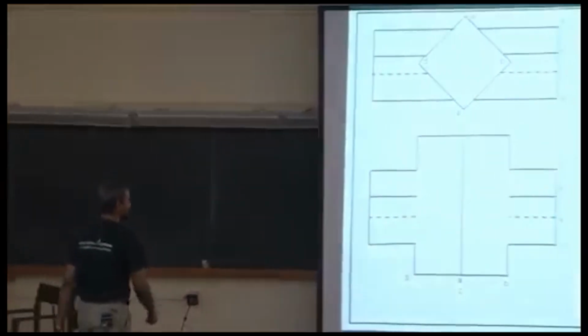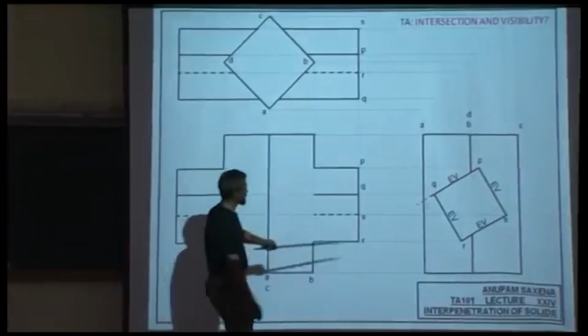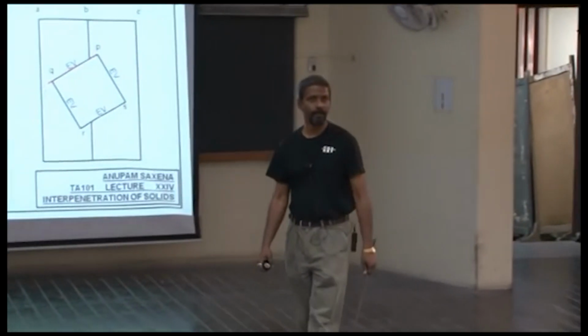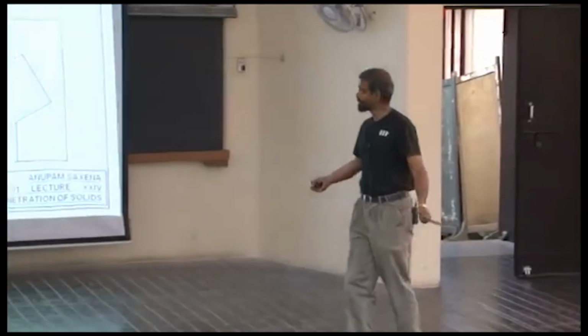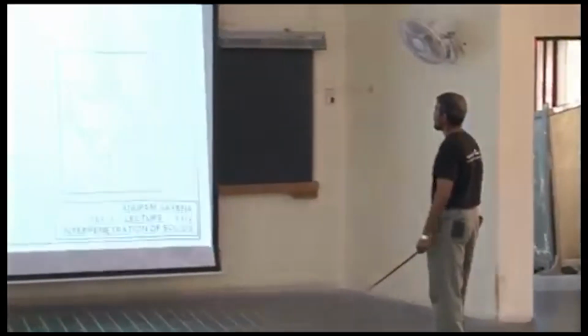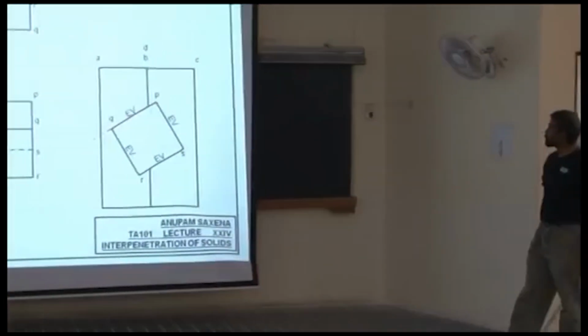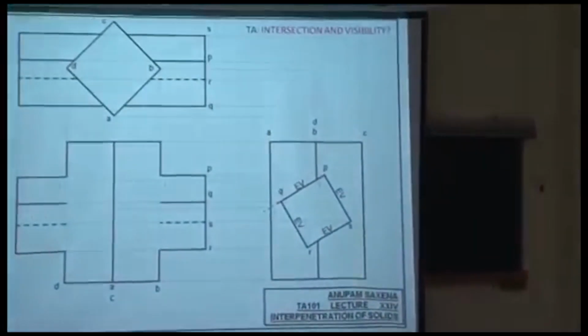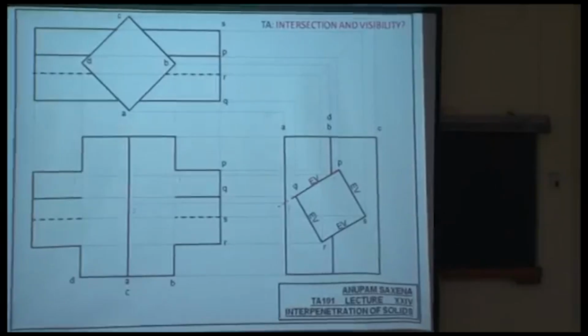This is my second section point, a pseudo intersection point, not real. Project this onto B and D. So this is 1 and this is 1. Notice that I am labeling my intersection points as I identify them and as I project them onto different views. Because if I don't, you know what's going to happen. Project point number 2. Point number 2 is going to be lying on edge A, not C, but A.